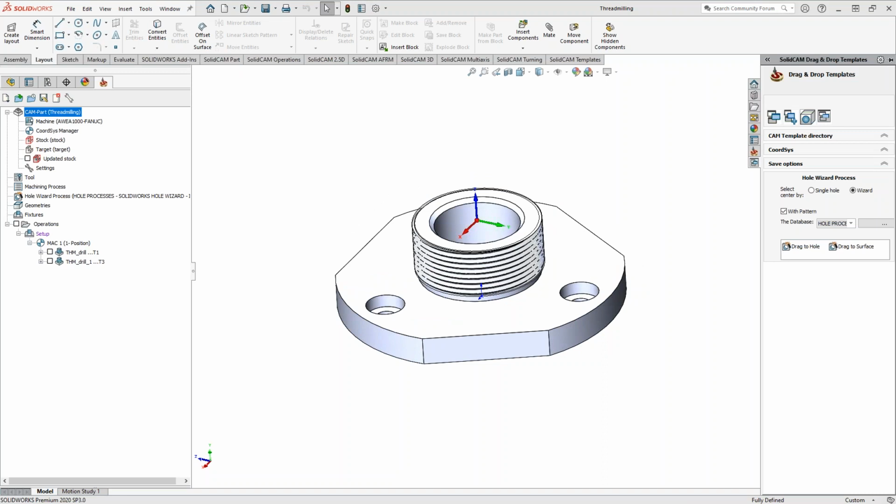And maybe the question might come up, because I have the question, since it's my own system: all that stuff is still there, but I know I've properly closed the files like we always tell people to do. So why would I still have stuff in my temporary folder? You can have stuff stuck in your temporary folder, like Mark said, if you don't properly close out of the file, if you just go up to SolidWorks and hit the exit button on the top right.